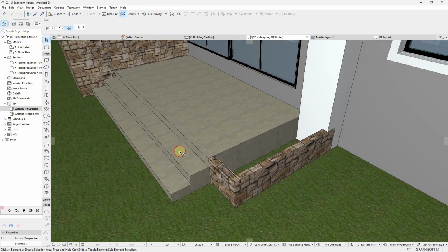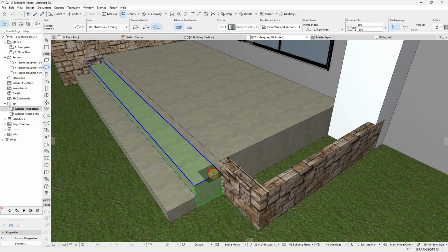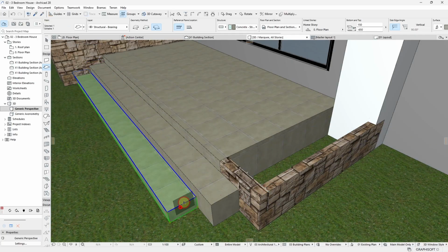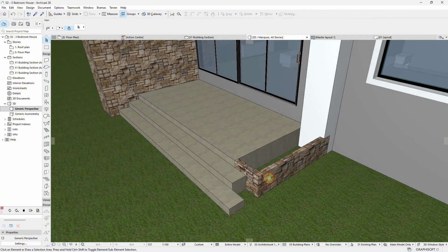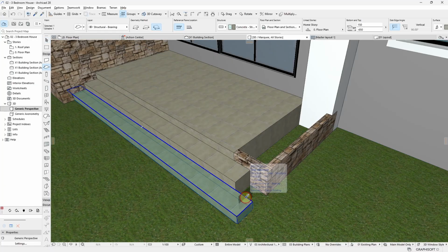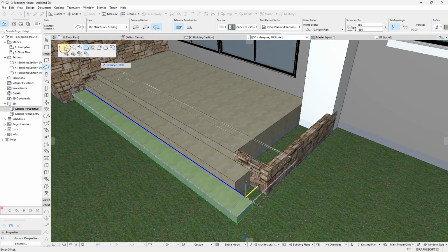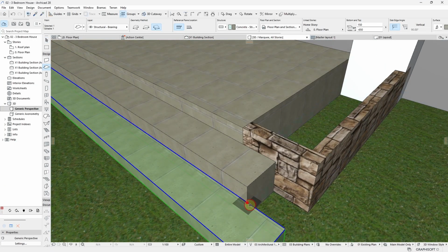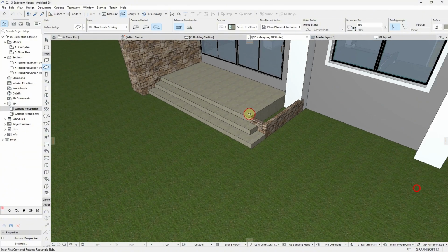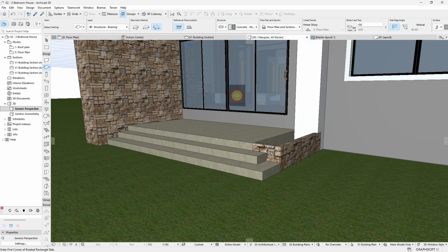So if you want to do a floating step, we're going to bring this out by 300 here, bring this out by 600. Then you do this, you cut this off here, then you push this to touch that part. So that when you do your floating step, at least it's curved around something. It's not just hanging in space.